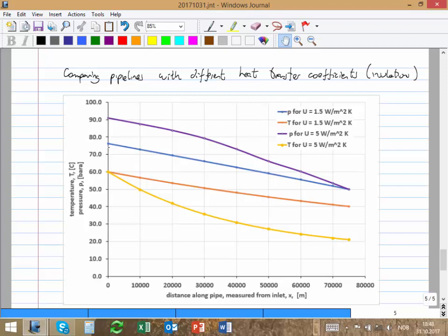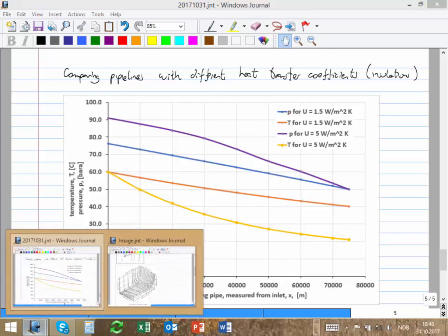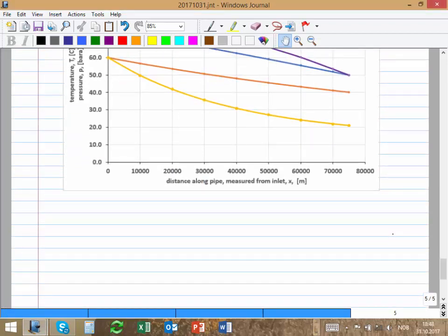And by that, let's calculate how much that is in watts. If you remember, I told you the power of the pump was Q times delta P, right?